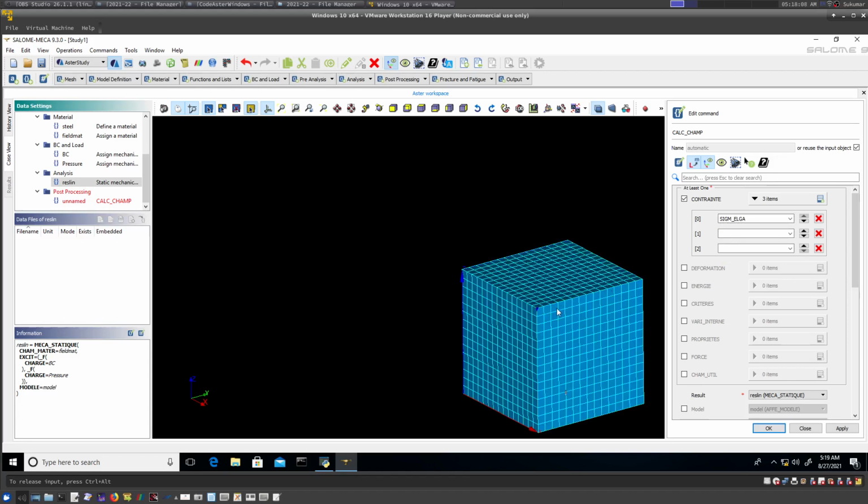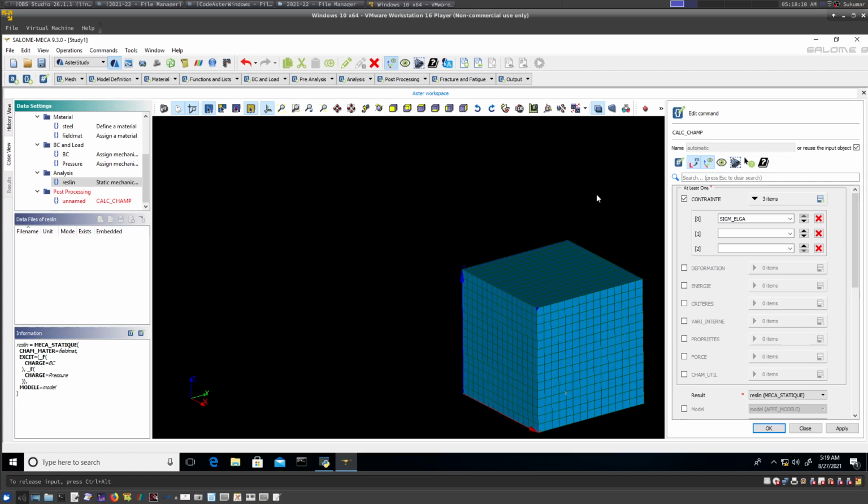That means all those integration points I told you about: in a plane quadrilateral element there will be 4 integration points, in an 8-noded brick element there will be 8 integration points. So in those integration points the stresses can be very easily calculated, because we can easily convert the nodal displacement to those element displacements at those points by using the isoparametric transformations.